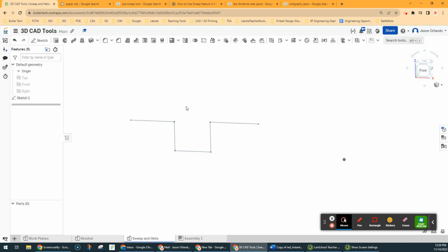It's not three-dimensional yet. So the sweep tool, what it does is it's like the extrude tool, but it follows a path. So it involves a second sketch that acts as a path. This is actually going to be my path. So I'm starting with a sketch. I'm going to rename it, and this sketch is going to be called the path. Okay. All right. Now what I need is something to extrude along this path. All right. Well, now knowing about planes comes in handy because I want to pick one of the two endpoints as the starting for this sweep.